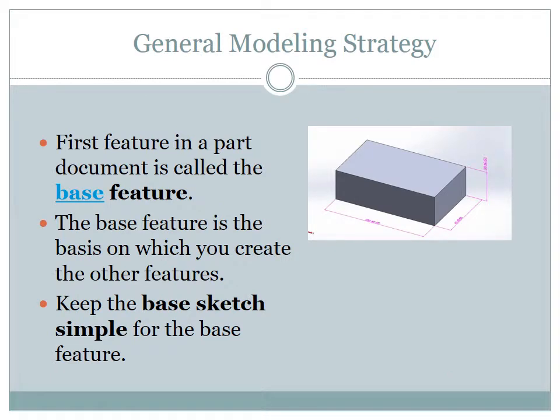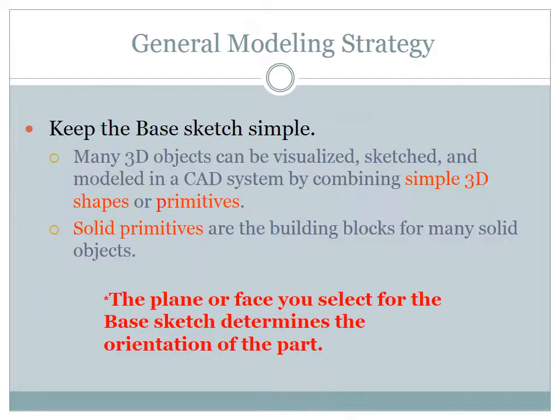Okay, so I'd like to start with a review of our basic modeling strategy. You know that the first feature in a part document is the base feature. The base feature is the basis on which you create the other features. Keep the base sketch simple for the base feature. What you want to do is keep it simple.